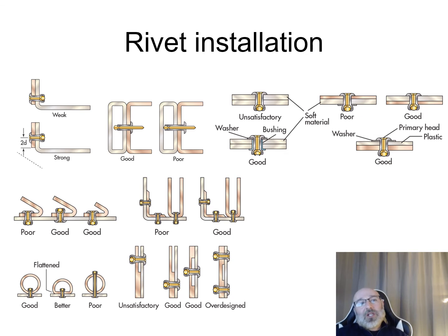So now I talked a little bit about the necessity of getting the right amount of pressure installing these, getting the right amount of rollover for the rivets, and this is something that, as I mentioned earlier, is a bit of a skill that's learned. This is definitely a skilled trade, installing these. Now, with these automatic machines, if you're in an assembly line in a factory, yes, you still need the skill to know what pressures to set things at, and you also need to be able to look at it and determine, is this good or is this bad?